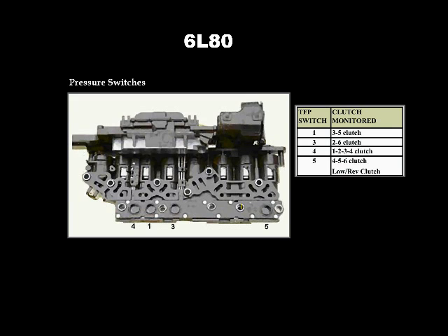And they also have a delamination issue with the pressure switches themselves. So again, if you've got a pressure switch code, which is a pretty common code on these units, take a hard look at the pressure switches for delamination issues. Good chance you're going to see one of them coming apart.